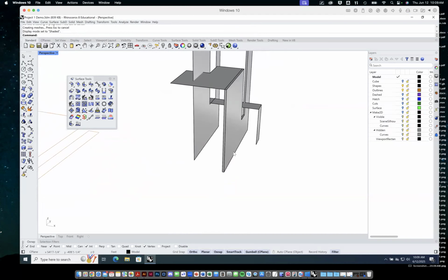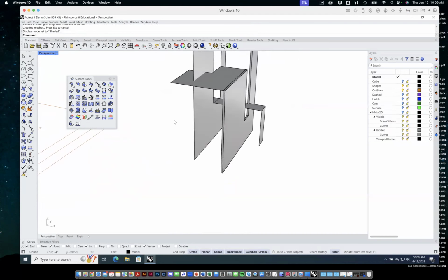Which tool did you use, Professor, for that? Under the Offset Surface tool? Offset, okay. Offset Surf, right? Can you point to which one of those is that? Offset Surf, it is this one. This is the icon, the button. If you're just going to use the command line, you can just start typing in offset, and you can offset curves, offset surface, offset SubDs, etc.